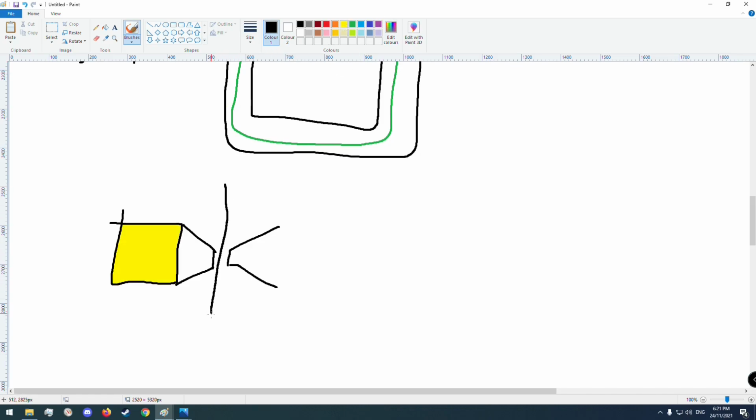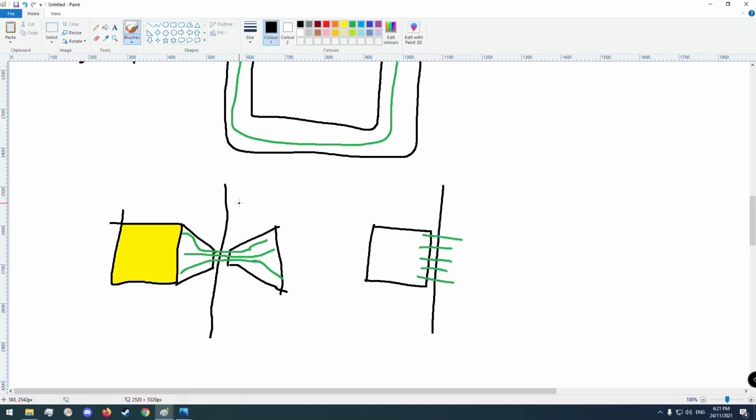So say if you've got your voice coil right here, and say these 2 voice coils are exactly the same and the amount of flux going through them is exactly the same. These voice coils will behave basically identically in a speaker, except this one right here has a lot more Xmax than this one right here. So basically, by channeling down the magnetic field, you get more excursion completely for free.